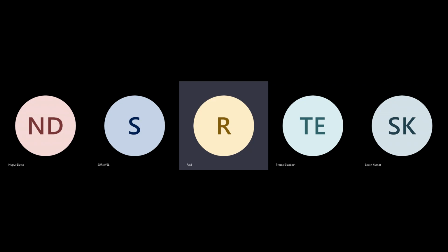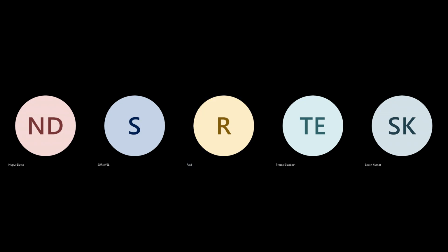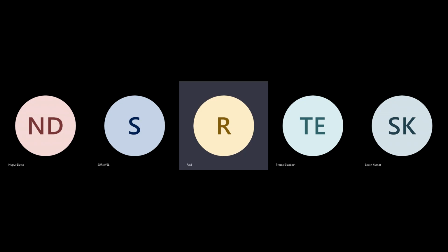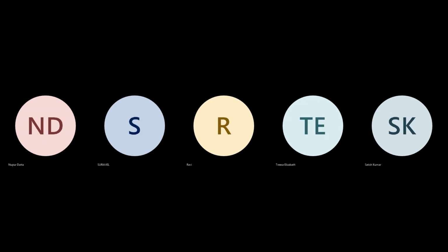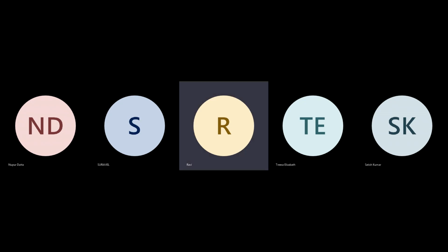If you're seeing that module is tightly packed, this module is very routing intensive. So I want to make sure that it is broken down properly. You can look at module padding also. You understood? Select this entire module and put some padding. Okay. Try to address as much as possible from a floor plan perspective.